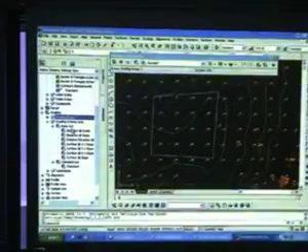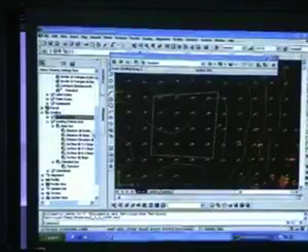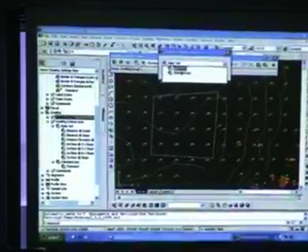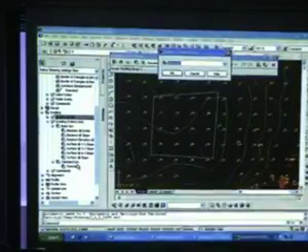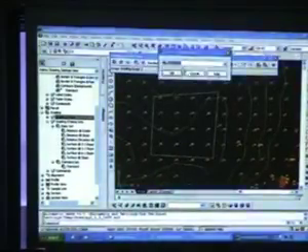So for us, if we want to have it go all the way up or down until it finds the original ground level, that falls under surface slope. So this is just to show you. So I'm going to switch this to basic set, because standard set has only standard, it's got like nothing in there. Okay, basic set is the one with the distance at grade, basic set slope. You just click on this icon, switch this to basic set.